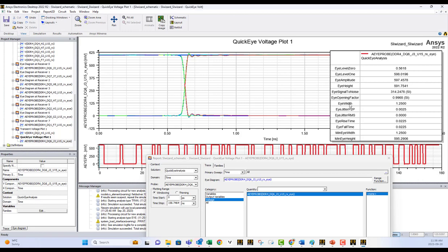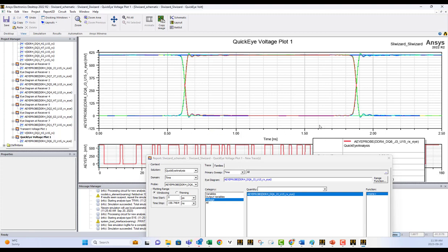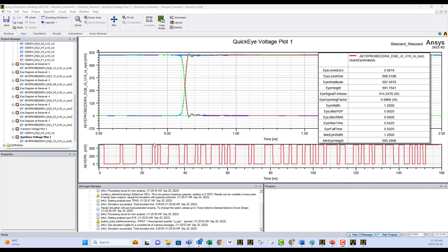You can also notice that it is a function of the interval time. This is very important because we will show another kind of eye plot as a function of unit interval, not as a function of time. In addition, you see here, it also plots the response from 0 to 160 nanoseconds. So you can see lots of data here. All of these are gathered and put in this plot. They overlapped. So you can see the eye diagram.